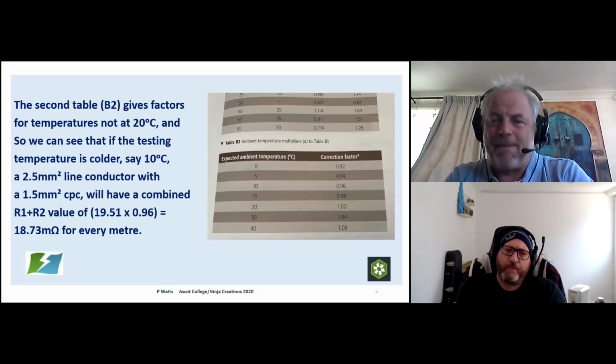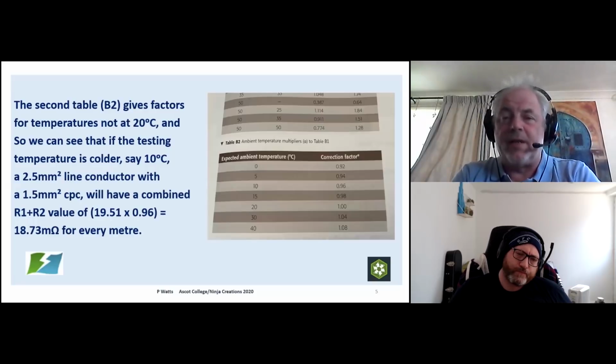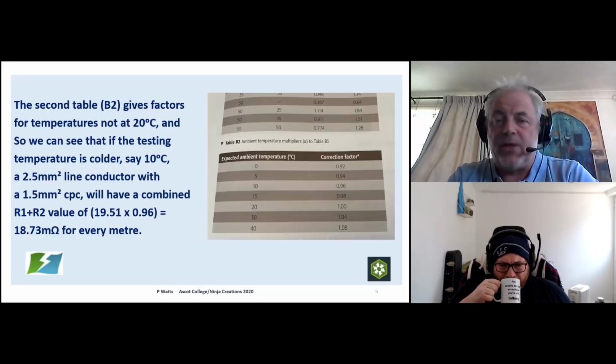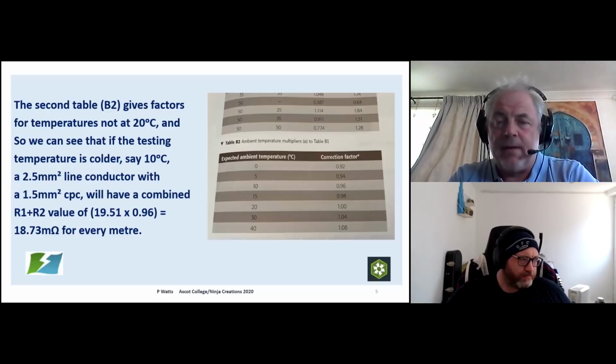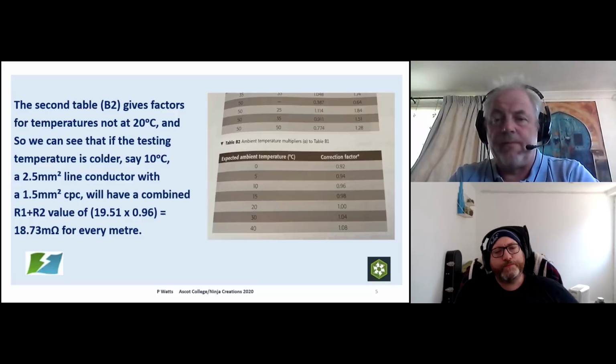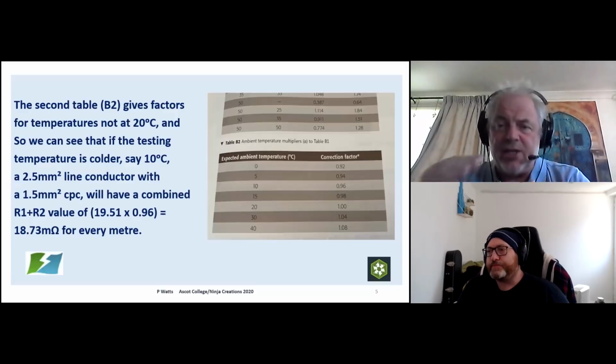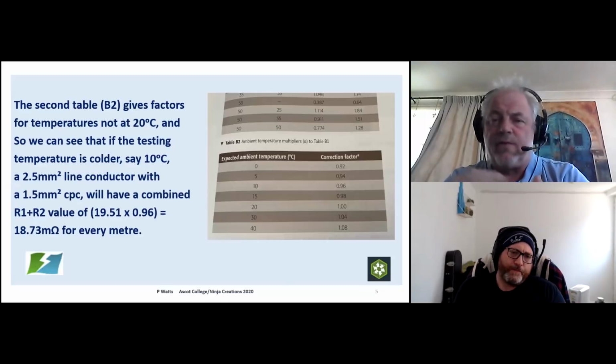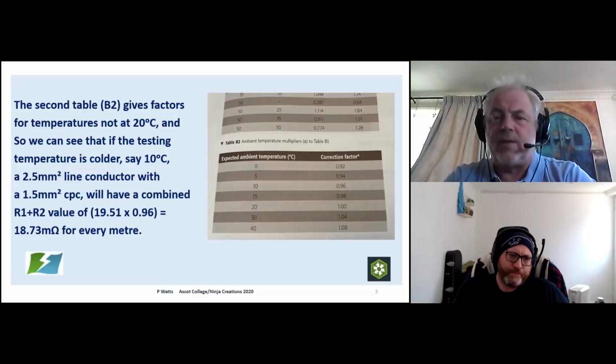So full currents will go up. Right? Yep. But then you've got the other issue, which is the classic problem we have, which is lofts. Which in winter can be absolutely freezing, and in summer can be like a sauna. So the actual change in temperature in a loft is ridiculous. It's a ridiculous thing to actually apply to our cables. Lofts can be sort of like 60 degrees.